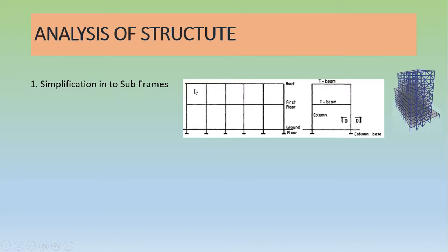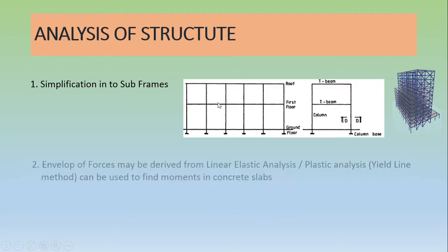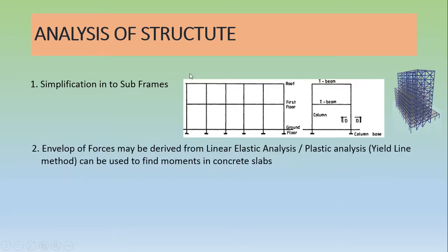Likewise you can simplify the structure into subframes, and also you can consider only this bottom frame. When we are considering this bottom frame, you have to put the additional loads due to these columns externally. Then only you can analyze this section, otherwise you can't.